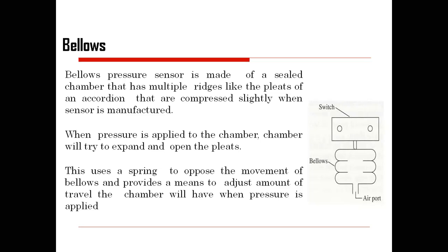Okay, so for the understanding of the switch I have represented this: how the pressure is increasing and how that particular pressure switch opens. In a similar manner, this bellow may be connected to your pressure switch, and when it moves beyond the limit, the pressure which we have applied as an input to the bellow will move it in the upward direction, creating motion across the switch, either for open or for closed, depending upon whether it is normally open or normally closed.